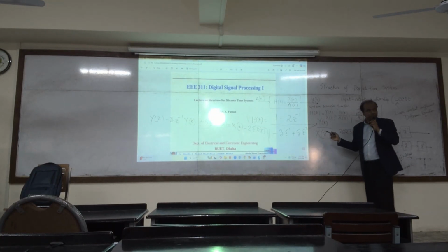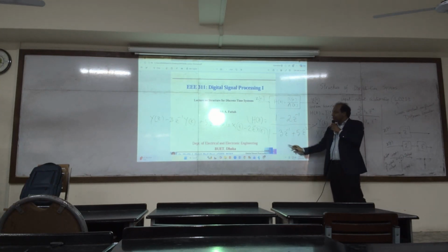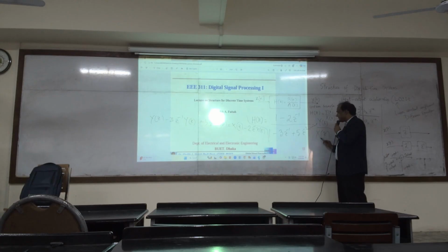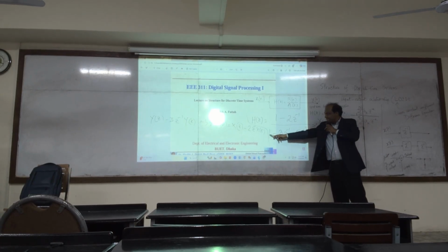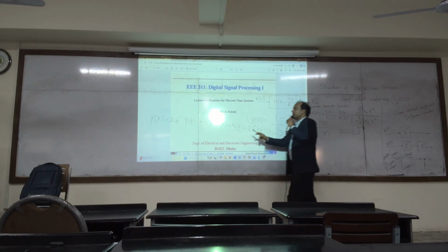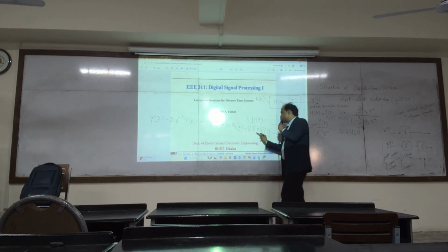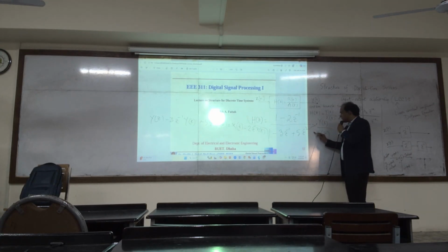Okay? Let's write, please write. So this is an overall transfer function, Y by X. Let's cross multiply: Y(z) minus 3 z inverse Y(z) plus 5 z to the power minus 2 Y(z) equal to X(z) minus 2 z inverse X(z).